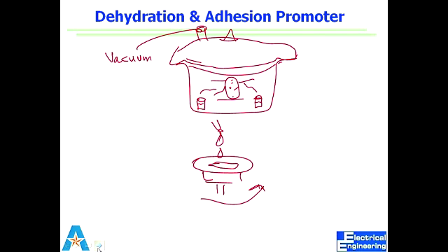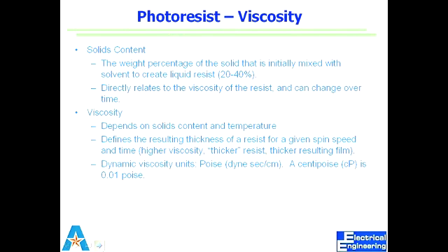The second is, can we apply HMDS on any kind of surface, not just silicon? Any surface. What's the big deal? But towards what end? To apply photoresist? Yes. It's silicon dioxide basically. Mostly you have silicon dioxide or silicon nitride. So it works both ways, because you have silicon in HMDS which sticks to any silicon-derived surface. So it can stick to silicon dioxide, silicon nitride, or silicon itself very well. Right? Let's stop here.